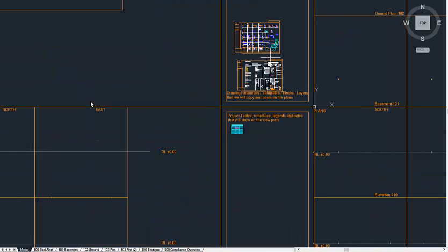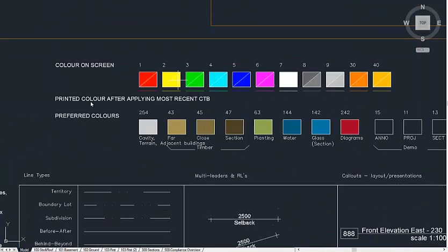But as a general rule, we follow AutoCAD colors, like red or number 1 will be quite thick, and gray, dark gray, and then we go down until we get to magenta, which will be also very dark but very thin. White will be the thickest and black, and then color 8 and color 9 will print opposite to what is on the screen with a dark background, because it's just a matter of contrast.